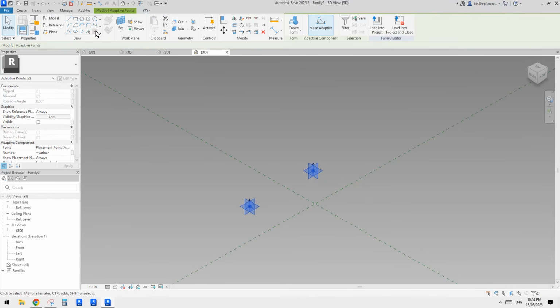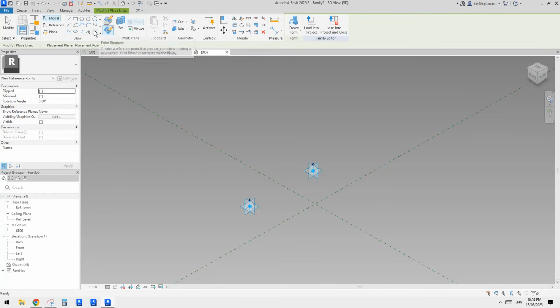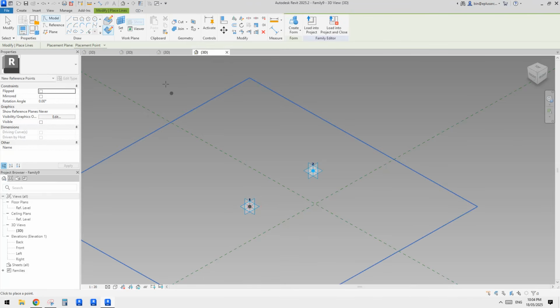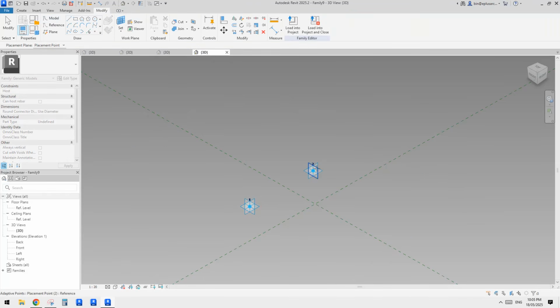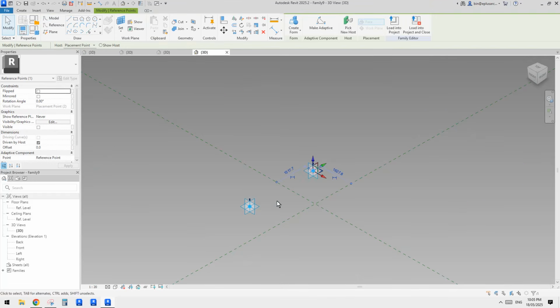And then we need to place a point, use draw on world plane, so onto the horizontal world plane on this point. Oh, hang on, let's do it again. Point, draw on world plane, set world plane, pick the horizontal world plane and place it. And another one, set the world plane and place it. And then select these 2.